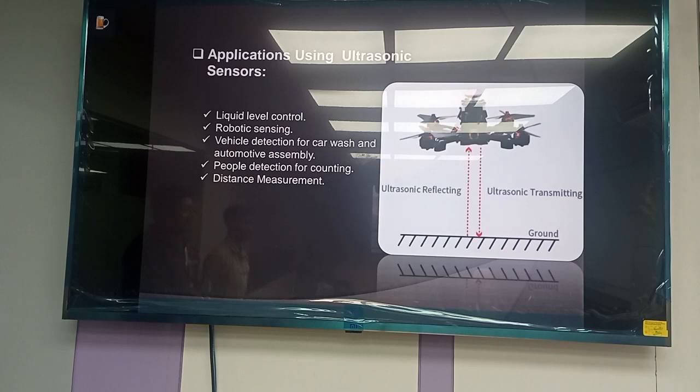First of all, in a liquid chamber there is the question of humidity, and the humidity will decrease the sensor life. Humidity also has a bad impact on the transmitter and receiver at the same time. So that's why it will decrease the lifetime of that particular sensor, and you would have to change it every month, maybe every week. It is not economically convenient for you. So that's the reason we will not go for that particular sensor.